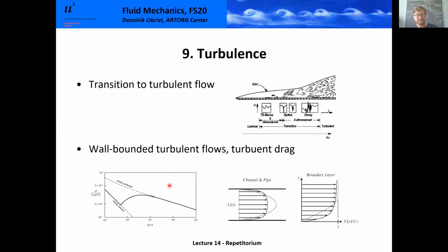We looked at what this means in terms of the drag coefficient. These are the drag coefficients we get for laminar flow, and then for a certain range of Reynolds numbers, we have to transition from laminar to turbulent. And once we're sufficiently high with the Reynolds number, and down here it is the Reynolds number, we go into the turbulent regime and usually have an elevated drag coefficient.